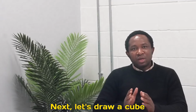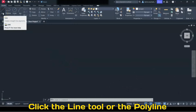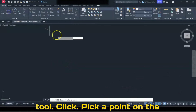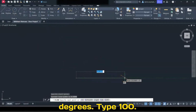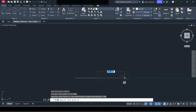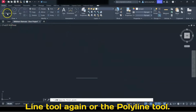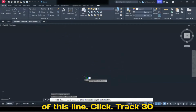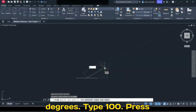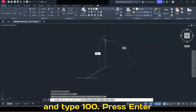Next, let's draw a cube box in isometric workspace. Click the line tool or the polyline tool. Click. Pick a point on the screen. Track 0 degrees. Type 100. Press enter twice. Pick the line tool again or the polyline tool. Click. Locate the midpoint of this line. Click. Track 30 degrees. Type 100. Press enter. Track 90 degrees and type 100.